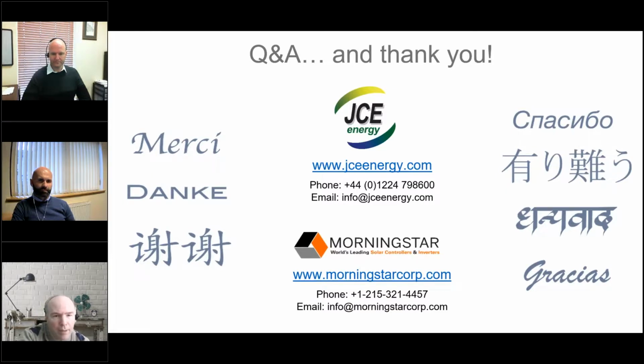I think very good. Let's see, we have a question coming in for Marco. Could you tell me in hot weather conditions, what type of solar modules will be best to use? In hot weather conditions. Right. Okay, we have worked many times in hot weather conditions. We have used every time the monocrystalline solar panels, which are working very perfectly. Of course, it needs to be said that at the higher temperatures, you need to oversize the solar panels because beyond generally 28 degrees, the solar panels derate their power. So you need to provide more power to overcompensate the higher temperatures. All right, very good. Thanks for that question.